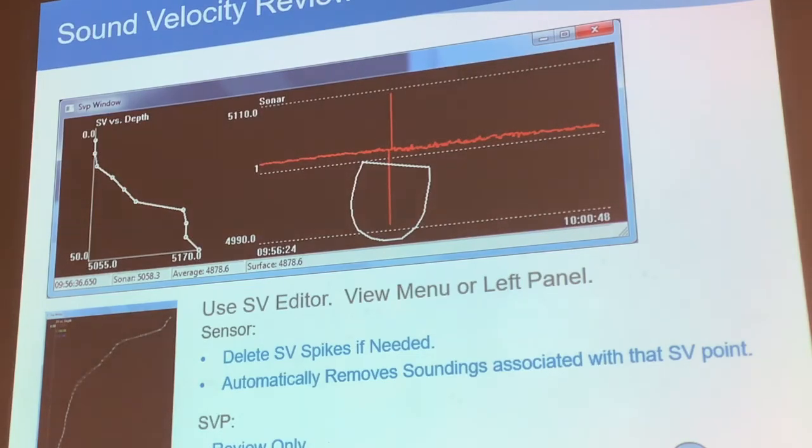But if you are getting between 1530 and 1480, it's still correct because that is very affected by salinity in the water, or it can also be sedimentation. You know, sometimes you have areas where certain sediments are coming in, which will affect the sound velocity of the water. So that's also a factor why some place where it's supposed to be fresh, it shows like it's salty. But each river is different, so you have to see the river dynamics.